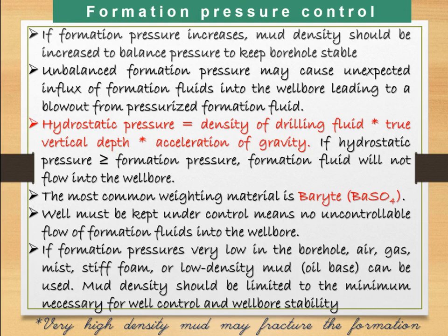This formation pressure tries to bring the formation fluid into the borehole, and borehole hydrostatic pressure can be maintained by adjusting the drilling mud properly, so that it can resist formation fluid coming inside the borehole.